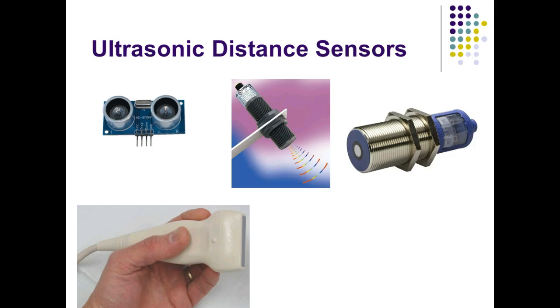It would be kind of like our car now. In the old days, all we had was a gas gauge. Now we have a light that comes on that tells us when our fuel is low. So you're combining two sensors there. You have an analog sensor that gives you the actual amount. It's usually a rheostat, by the way, or a potentiometer. And then we have an analog to digital converter that says, okay, if the output of that pot gets below this voltage, it means you're low on fuel. So most of these sensors are analog sensors, but a lot of our control is done digitally.